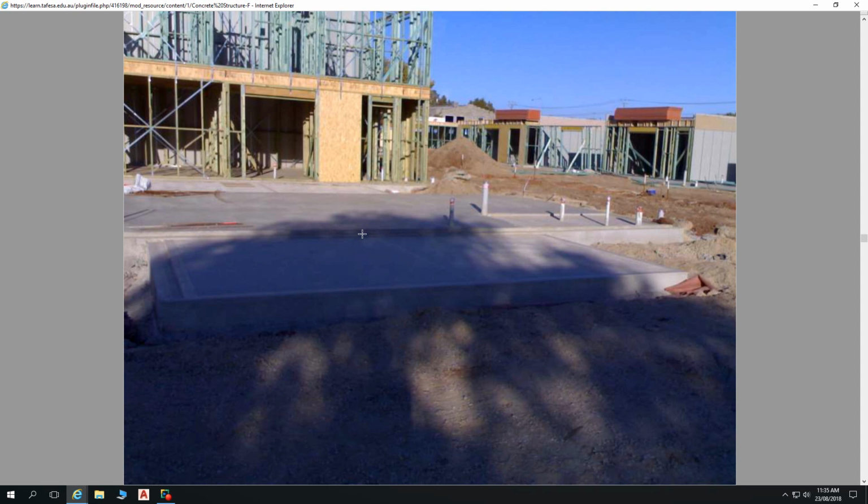Anything else people can see in that picture that's of interest? Anyone at this stage? There's not too many noggins going across, are there? No, there's not too many noggins. The thing with noggins is that your noggin spacing has to be at 1350 centres. So I see that, and straight away I go, oh yes, 2700 high ceilings, because we've only got one row of noggins in there. If we're going to 2900 high ceilings, then we need 2 rows of noggins in there.